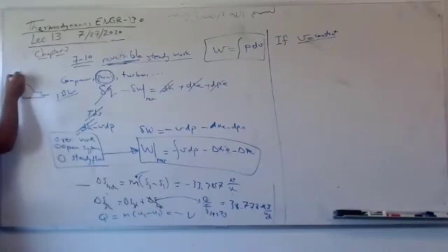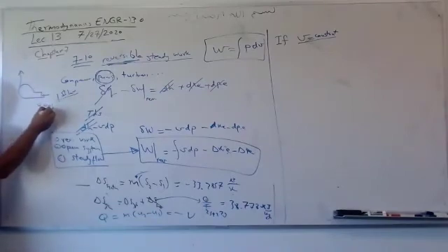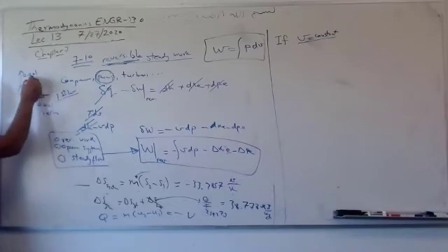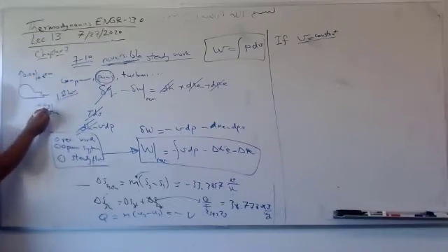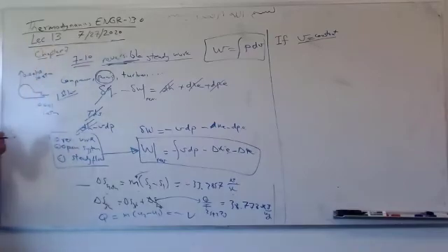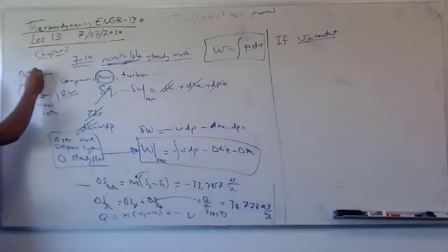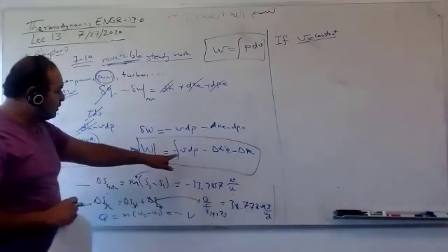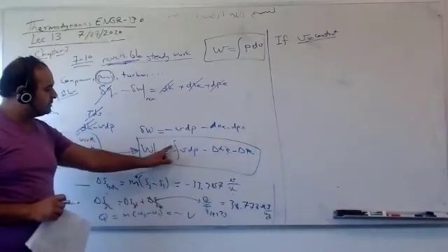that compresses water, almost coming in at 0.001, going out at 0.001. Density does not change, almost. The pressure was 1 atmosphere, can be like 5 or 10 atmospheres. There is almost nothing changing, less than 5%, 2%. Almost V1 equals V2 in a pump. So you can assume V equals constant like this. So if V equals constant, this can be out.